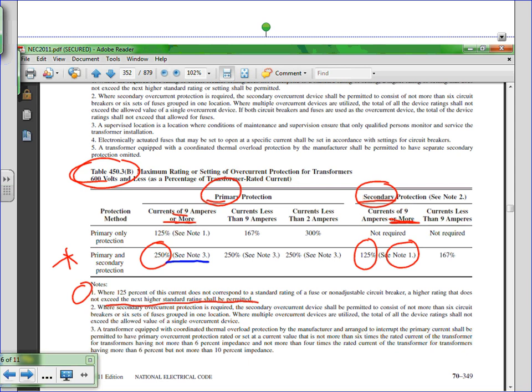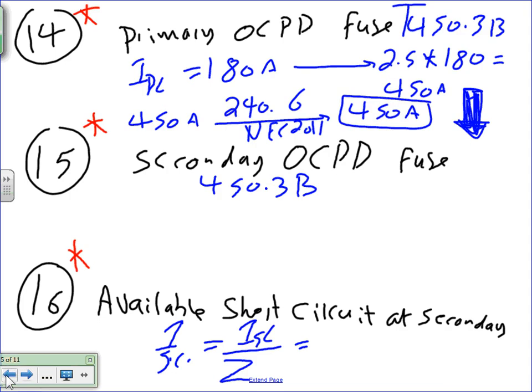All right, so there are standard sizes for fuses. Standard sizes, the table is both for fuses and circuit breakers. Non-adjustable circuit breakers. Okay, everybody knows why we didn't go, in this case, William, in this case, I don't have to go up or down. I hit the jackpot, so I don't have to go up or down. But if it was, say this was 420, you have to go to 400. Say this was 460, you have to go down to 450. Can I have thumbs up? We got it, Chad, move on. Yes, no? Phil? Good? Three thumbs up at once? Oh my God.